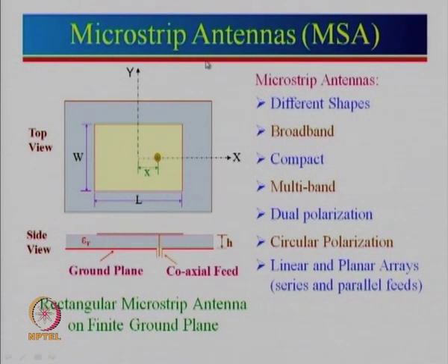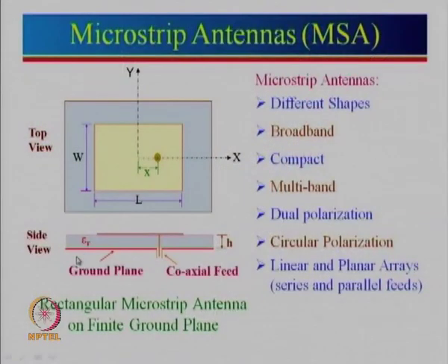When we talk about microstrip antenna, we will talk about different types of feed there. And by choosing a proper feed point, we will be able to match the impedance. So, in fact, this particular configuration does not require any external impedance matching network. It does not require any balun, which is balanced to unbalanced, and it is such a simple configuration. All you have is just a very thin printed circuit, and this printed circuit will have very less weight, less volume. It can be bent around.